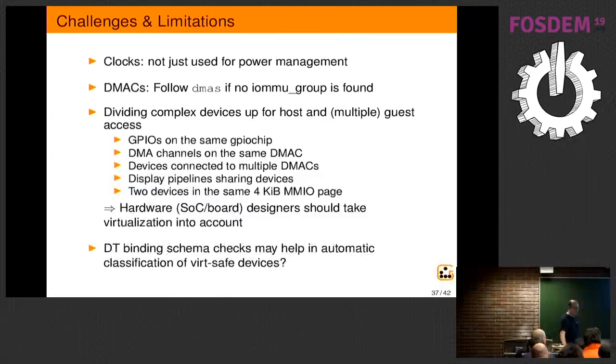There are still some small difficulties to handle. Clocks are not always used for power management. Some drivers really need to know the clock rate and maybe multiple clocks. For that, we may need some other solution. This does not yet support devices that don't use DMA themselves, but use a DMA controller.